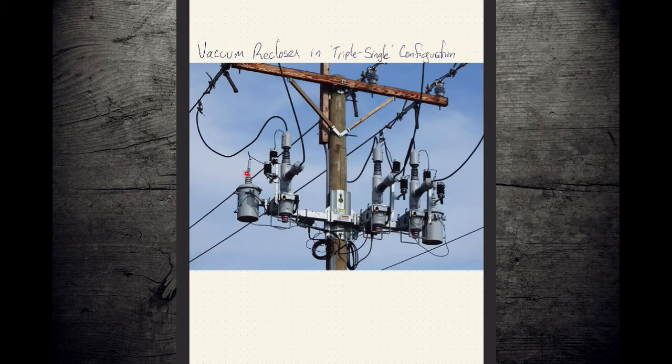Over here, we've got PTs. So here we go from our primary side voltage, and this will step that down to 120 volts and send that down to the control cabinet, which will be located somewhere near the base of the pole. Usually right about 6 feet high, you'll have a control cabinet mounted on the pole. And so those PTs are going to send their signals down there, and the relay inside, right? This is just at the top of the pole. This is just a switch. It doesn't have any intelligence to it. At the base of the pole where the relay is mounted, that's where the intelligence lives.